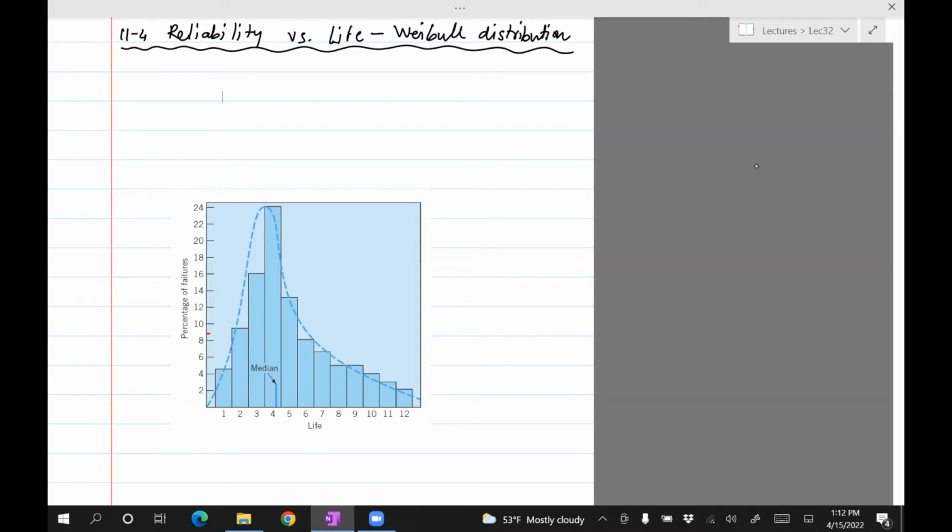machine elements follow a normal distribution, which means that if you randomly pick a diameter in a sample of 1,000 and the nominal diameter is supposed to be 1.5, then you will see that most of the diameters are in the range of 1.5. In fact, you will see that 95% of the diameters are within plus or minus 3 sigma, where sigma is the deviation. So you have this thing called normal distribution, which explains most of these things. In the case of failure of ball bearings, when people did these experiments, they found that failures follow what is known as a Weibull distribution.